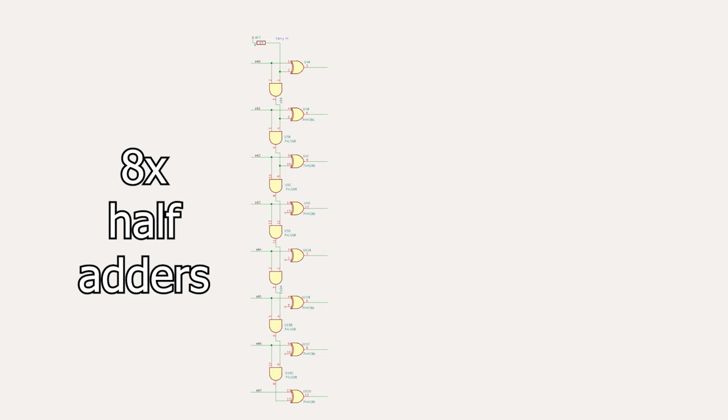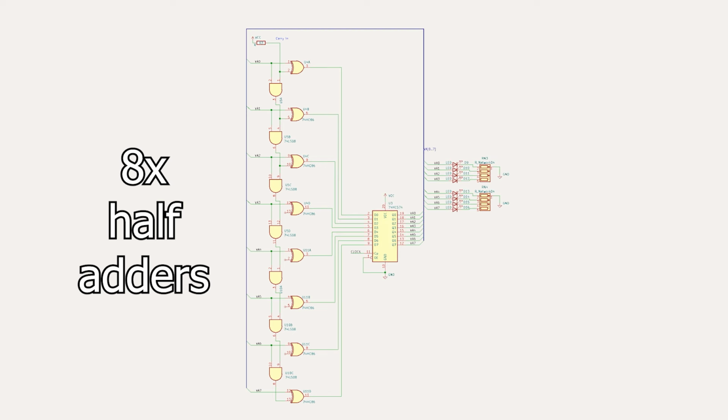This machine has 256 states, where each state is a number between 0 and 255, hence, it's a finite number of states. Now, it's also possible to make up a counter with a binary adder in place of the EPROM, which is what I've shown in the middle here. It works the same, but obviously the EPROM is much easier to change, say to count in binary coded decimal, which would require extra logic with the adder-based circuit.